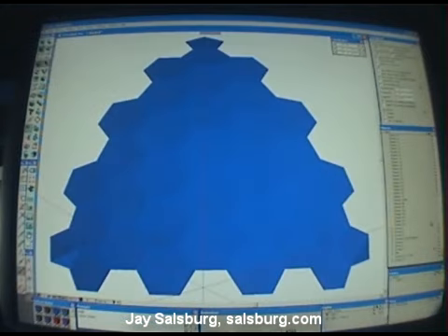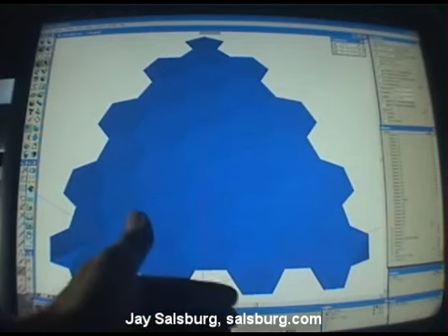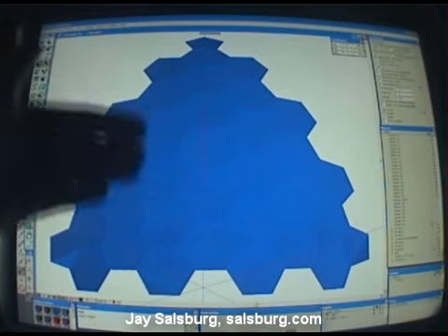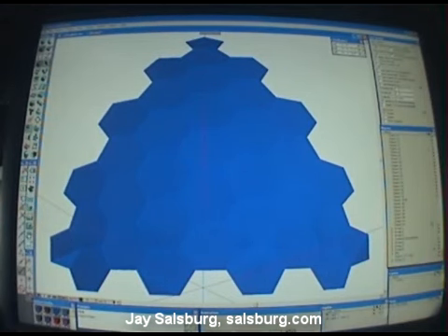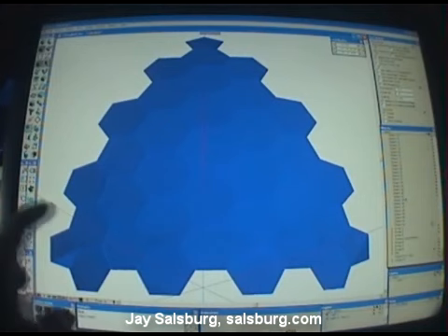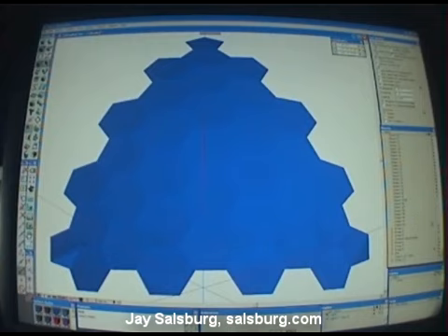By adding 6 groups of struts, we can achieve omnidirectional support of these skin pieces. But we can alternatively, instead of using struts, use sheet metal. By combining the sheet metal and using seam welding, you can weld the sheet metal. What I mean by sheet metal, they may be as thick as an inch, depending on the strength needed.